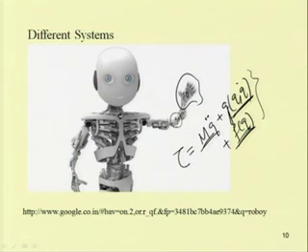Sometimes it is not possible to model this equation correctly. For that purpose one has to use a control parameter, or one can use control K p, which is the proportional gain, so K p into E. If there is some error, then plus K d into E dot, where E is q desired minus q actual.